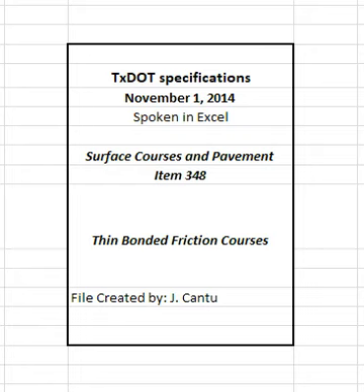4.7.1 Weather conditions. 4.7.1.1 When using a thermal imaging system, the contractor may pave any time the roadway is dry and the roadway surface temperature is at least 60 degrees Fahrenheit. However, the engineer may restrict the contractor from paving if the ambient temperature is likely to drop below 32 degrees Fahrenheit within 12 HR of paving. Provide output data from the thermal imaging system to demonstrate to the engineer that no recurring severe thermal segregation exists in accordance with Section 348.4.7.3.1.2, Thermal Imaging System.